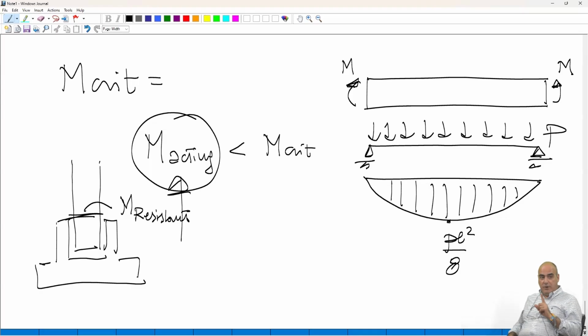Also because remember this, especially in earthquake, if you over-design, it means that you make a stronger element, but it also means that you make a stiffer one. Earthquake, as we have learned this morning, is not a force. Earthquake is a non-uniform motion of the ground. If the motion is non-uniform, it means that you have an acceleration.